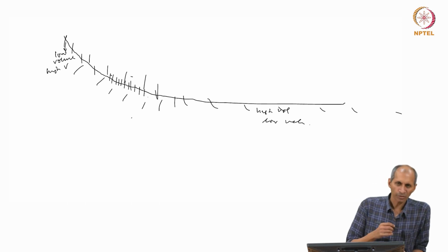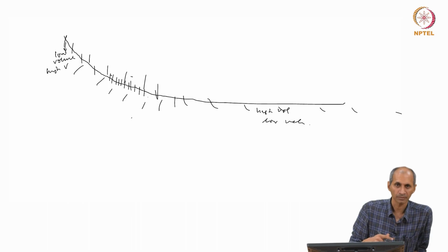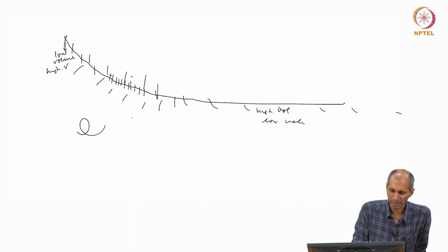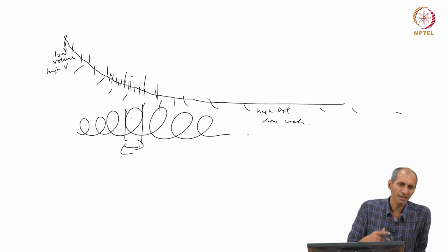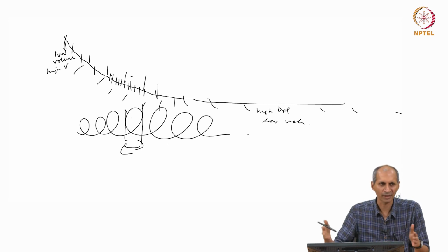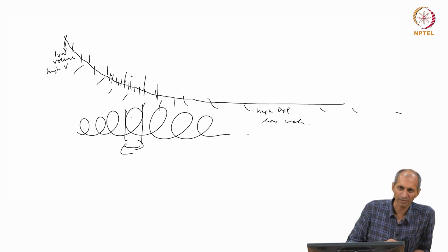Now, a river is flowing. It is very unrealistic to consider a river as a well mixed system, because what we consider as well mixed means there is backflow. I put something here, it goes forward and comes back. That may not be happening in a river to a large extent. You may have a little bit of backflow because a river may flow like this, but the scale of this convection is not very high. But I think a lot of times we do not have a choice, otherwise our computation becomes very, very difficult. So, they will generally break it up into this kind of system.